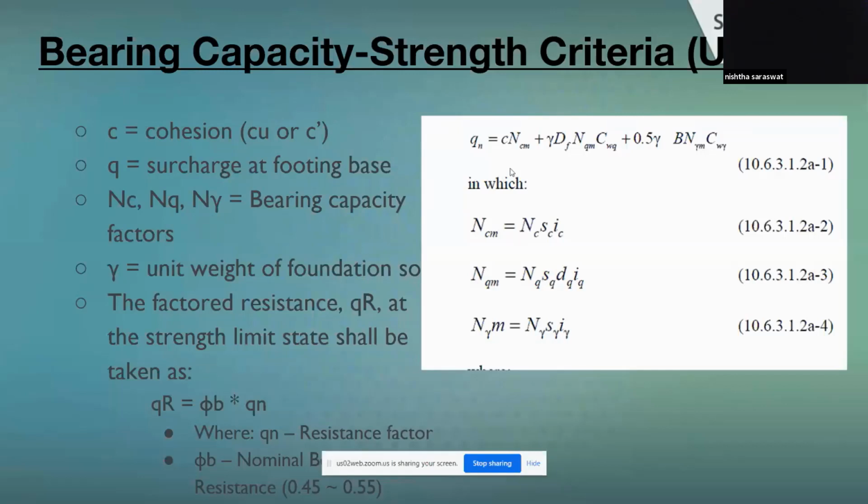I would also like to discuss in detail the various types of soil before we go into the description for their calculation of bearing capacity. So the soils can typically be divided into three types, which is granular soil, which consists of gravel and sand; fine grained soil, which consists of clays and silts; and organic soil, which consists of peats and loams.